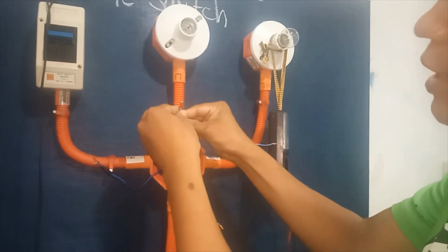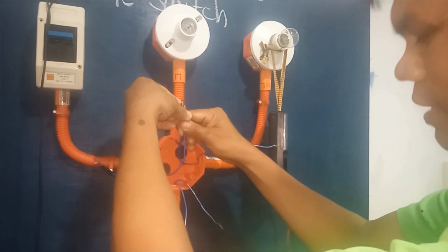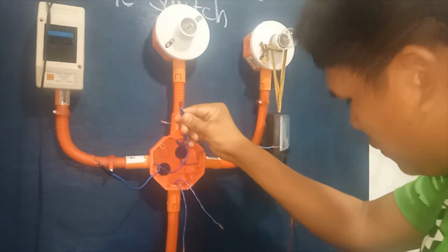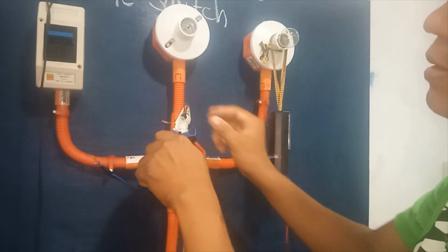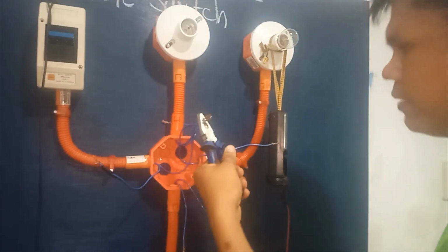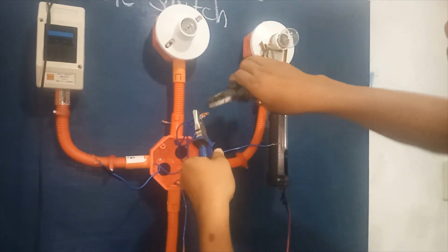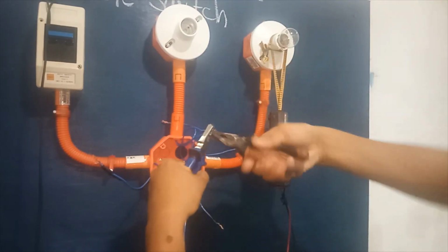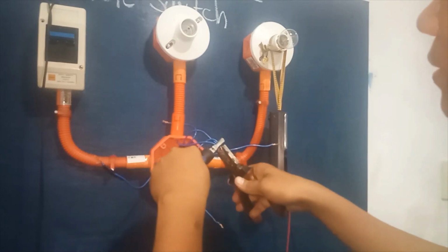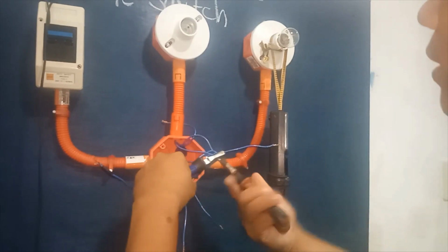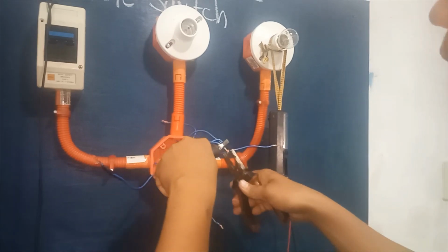Okay? So ito guys, hinahawakan ko na siya, and then we will hold that one with another piece of the plier, like that, and then twist here with the use of the other piece of the plier. So meaning to say, there should be a pair of pliers, a set of pliers, to execute the splicing process.